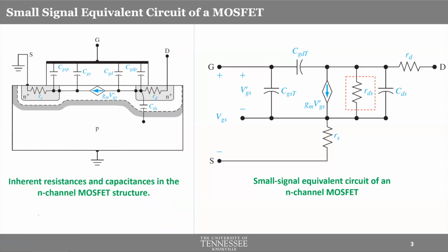And because of that, we will have some parasitic capacitances between this gate and source contact, which is represented using CGSP. GS stands for gate to source and P for parasitic. So, parasitic capacitance between the gate and source. And again, parasitic capacitance between the gate and drain, CGDP. Okay, so these are the two components which we will use to represent the overlapped nature of the device.